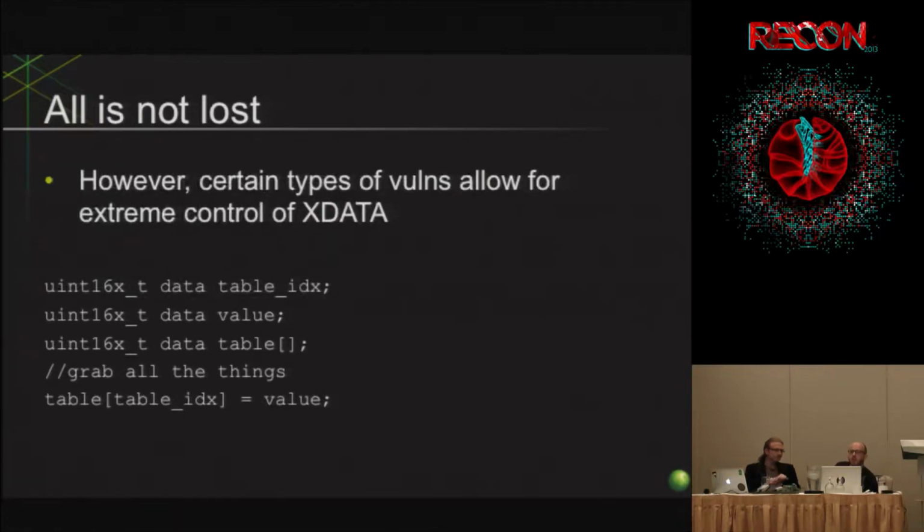So this is actually perhaps relatively common on this kind of stuff. You think about when you're implementing a spec, like the spec that's used over that optical port, and it's used to shovel metrology data back and forth. It's called ANSI 1219. It uses this concept of tables, and basically it's these huge tables that have variables in them, and you store some things in them and you read some things from them. And that's how the power company knows how much power usage your smart meter is using. You think about how would you implement that?